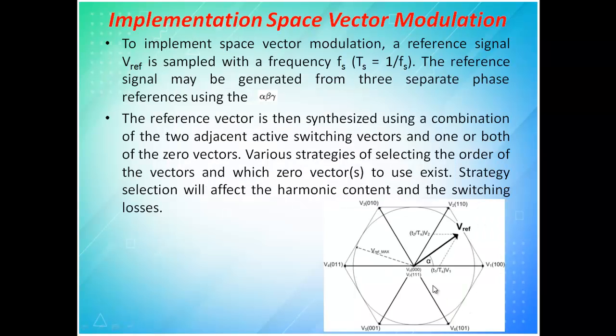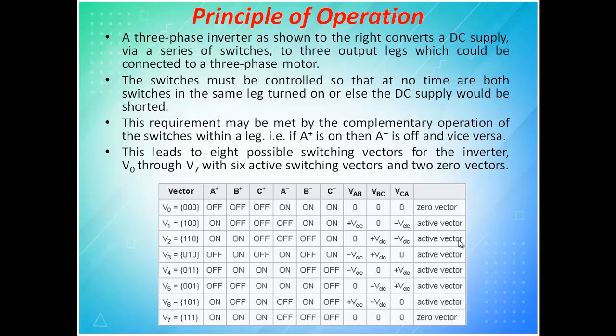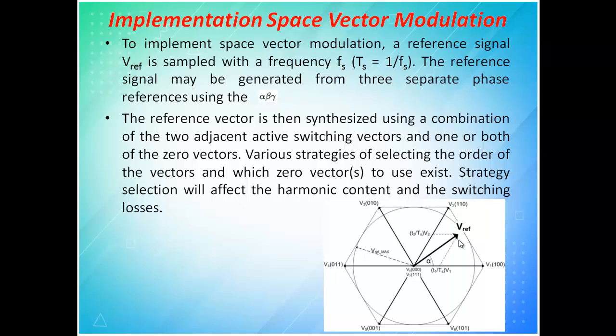So I can even draw it like 0 to 360, and in this 0 to 360, what they do in space vector is, first they split it into 6 parts, 1, 2, 3, 4, 5, 6, and each part they call a sector, and in that sector they decide the value of the firing pulse. First they will take one reference 3-phase supply, and from that reference they will identify at what position of the 3-phase sine they are. Sine is time varying. So they will find the sector, then from that particular sector they will start firing.